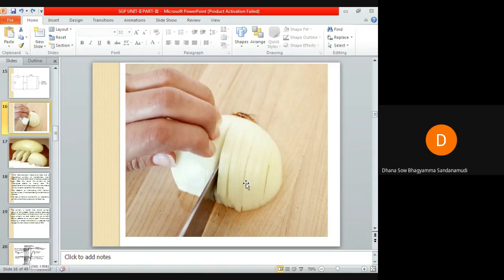circuit breaker has to interrupt low inductive currents, since the magnitude of that inductive current is very small when compared to the rating of the circuit breaker, the available deionizing force will be sufficient to interrupt the current straight away from its high value to zero. So if this is the loop, you can say a person is chopping here, is cutting here. So the current from this peak, as he chops from top to bottom,